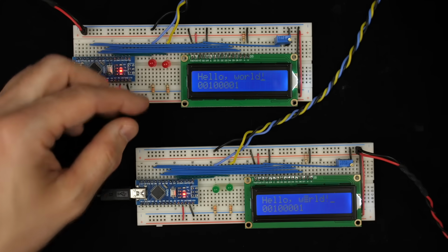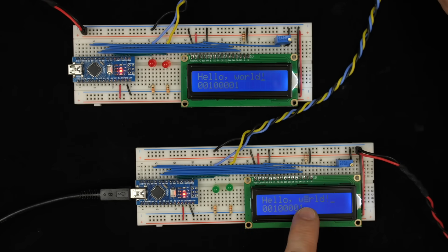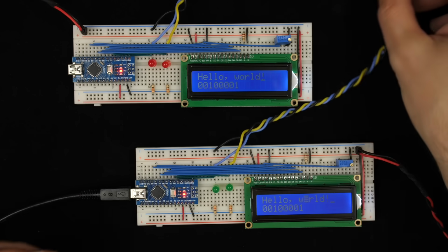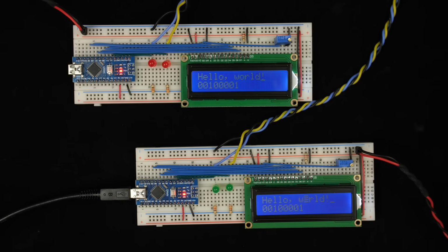And so I had that off frame and just introduced a little bit of a bit error right there in the middle of the message. And you might think, well, that's not very realistic. I mean, how often are you sending a message where someone has a way to interrupt the message while you're sending it? But the reality is any communication system is susceptible to errors. And in fact, any communication channel has a theoretical maximum bandwidth, and particularly as the bit rate gets close to that theoretical maximum, then the channel becomes more susceptible to noise. And noise can cause errors like that, where you miss a bit or something is off a little bit.